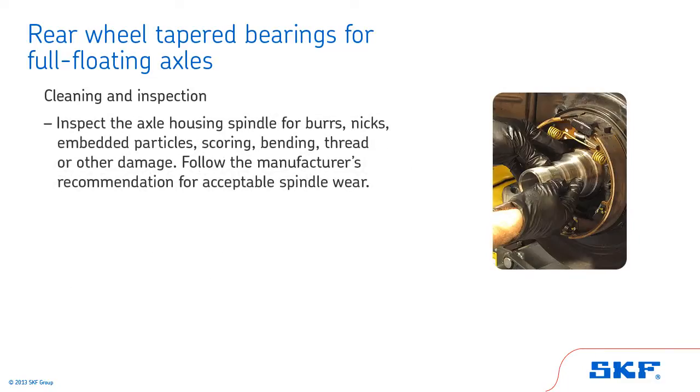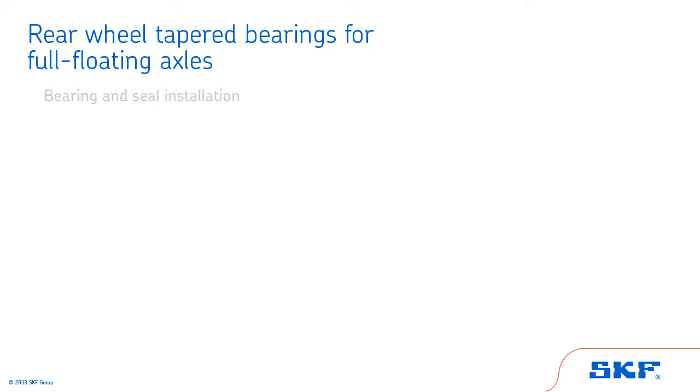Inspect the axle housing spindle for burrs, nicks, embedded particles, scoring, bending, thread, or other damage. Follow the manufacturer's recommendation for acceptable spindle wear.